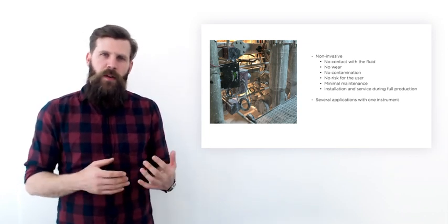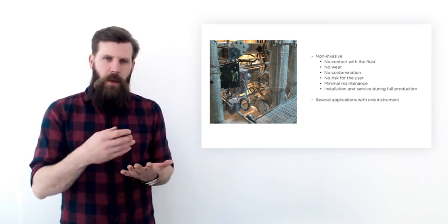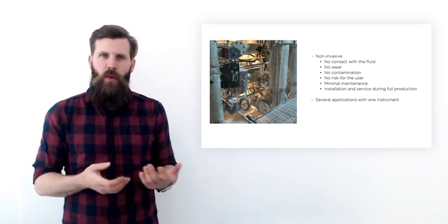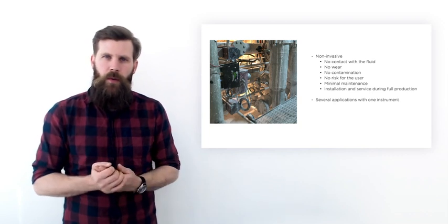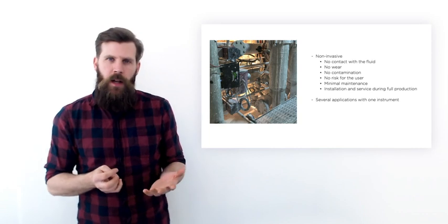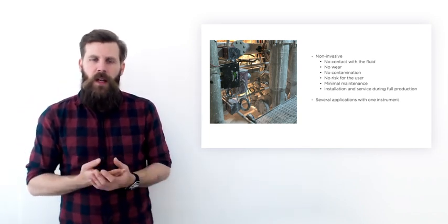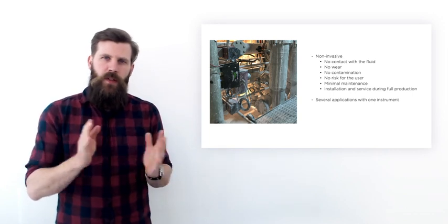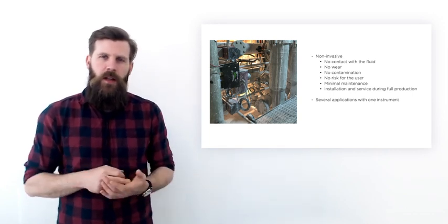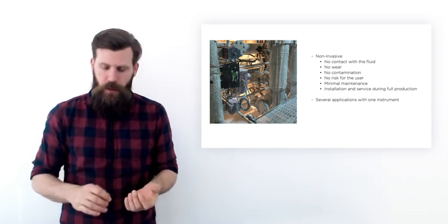On the other hand, there is no risk for the user, neither during installation nor during maintenance or any other work you perform on the pipe or the instrument. Maybe the most important part is that you can install during full production. So basically what we need is to remove the insulation from the pipe and then we can install the instrument, nothing more. A power outlet as well, of course.